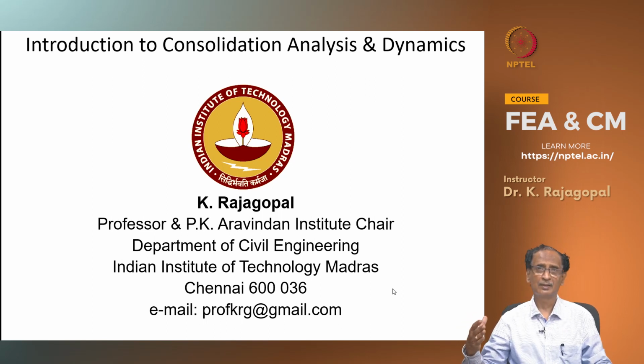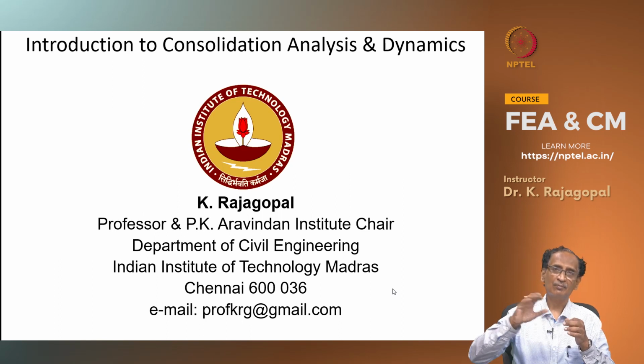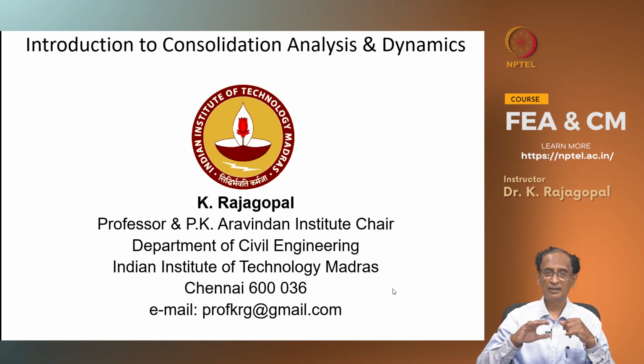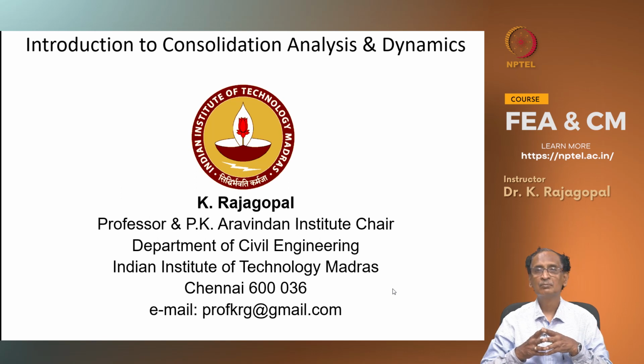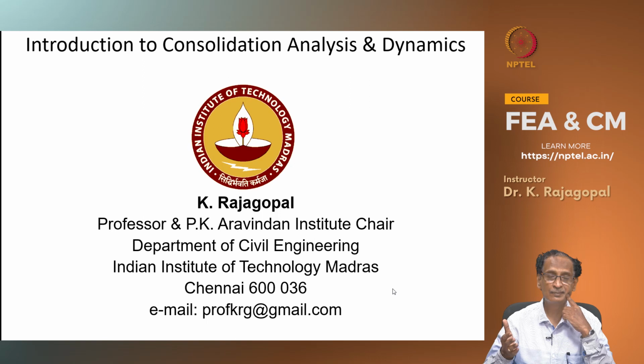In the previous two classes we looked at elastic plastic constitutive modeling, and we have seen how to derive the constitutive matrix during the plastic flow. The fundamental equation we have seen is based on the requirement that the yield function value should remain constant, or the change in the yield function value is 0, which we called the consistency condition.